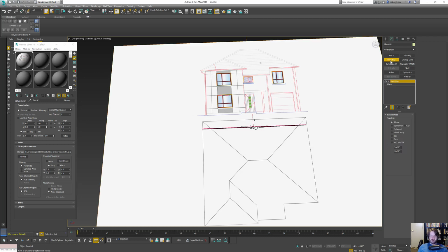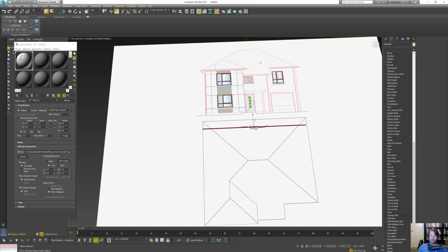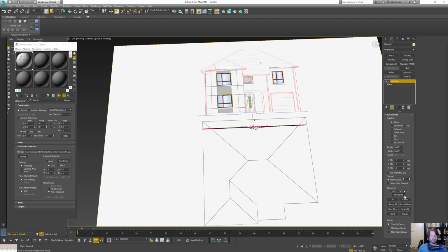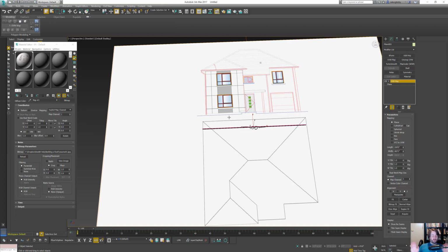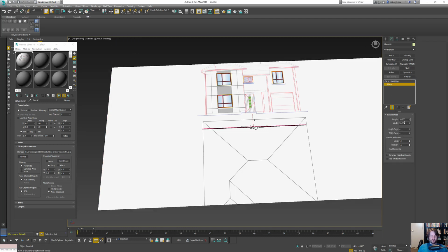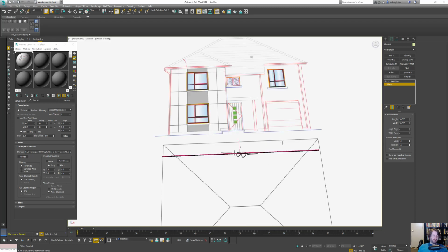And now what I do is I put a UVW map modifier. This is the exact same thing as if you come here and go down to UVW map. I just have it as a little button because I use it a heck of a lot. Okay, so this is good, but we don't want to type anything in. These dimensions are the same as they are on the plane, you'll see. But what we want to do is get our pixels 1:1 so they're not squished. So we're going to click bitmap fit. We're going to click our bitmap, and it's going to look at the resolution of this, and then it's going to apply it. And I've gotten pretty good at guessing, so it shifted a little bit. But now, no matter what, as long as you're previewing up the stack, it's not messing it up or anything.